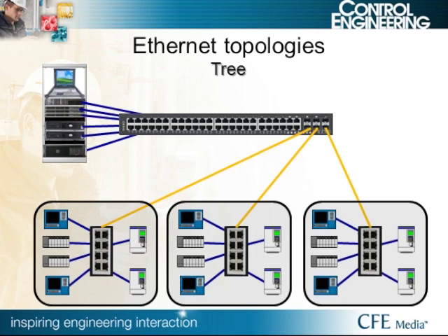The switches in the panels are industrial grade so that they have extended temperature ranges and use the same 24-volt DC power as the other devices in the panel. This topology follows the TIA 1005 standard to keep the switches as close to the devices as possible. This example is a combination of SCADA and control, so all the switches should have IGMP snooping enabled. But what this topology is missing is media redundancy.